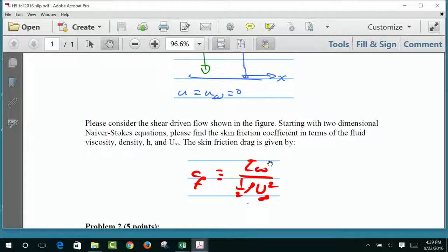In case the problem simplifies to there is only one velocity gradient throughout the velocity profile, that's fine, perfect, which is the case in this scenario. But in the midterm, in case I have pressure-driven flow, that's like flow between two parallel plates, and you are pushing it by pressure gradient. You're not pushing it because the wall is moving. No, the two walls are fixed. It's just that there is pressure gradient. High pressure in Stillwater, low pressure in Tulsa, and the water is flowing from Stillwater to Tulsa. That's called pressure gradient. That's pressure-driven flow.